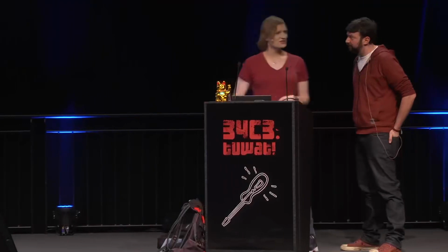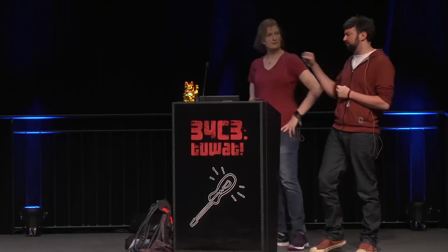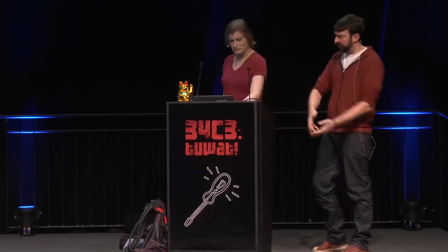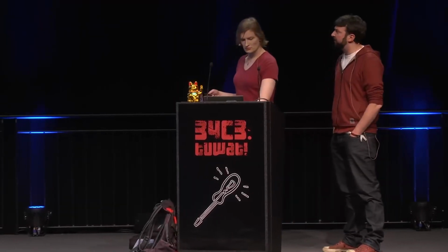It's kind of difficult to see on the board, but if you look over here, here's all the configuration settings you would use. These are preconditions that determine when an individual USB event is generated. So you can go into this interface now and say, when this GPIO pin goes high, and this one goes low, and this one happens on the 4th time or whatever, those complex conditions that we're talking about, the software will then trigger the ChipWhisperer to do its thing. Right.